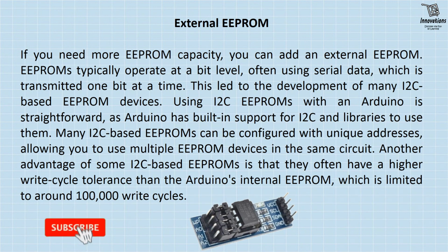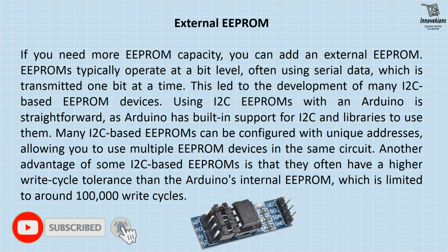Now if we speak about external EEPROM, if we need more EEPROM capacity than what is in the internal EEPROM of an Arduino, we can add an external EEPROM. EEPROMs typically operate at a bit level, often using serial data, which is transmitted one bit at a time. This led to the development of many I2C based EEPROM devices.